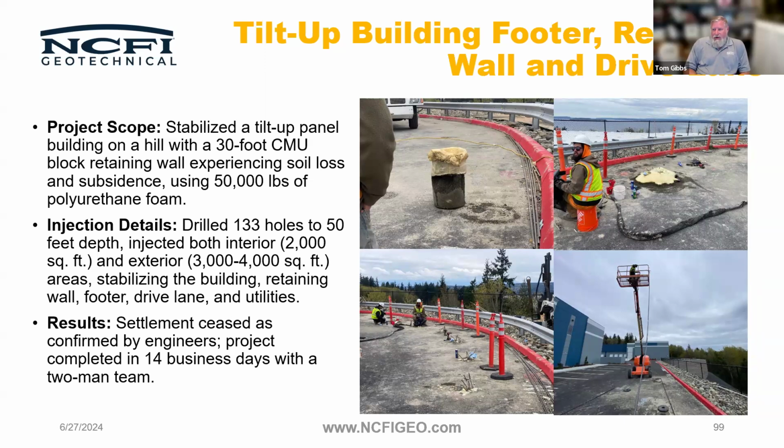But if you were doing one where there's literally no concrete or even asphalt, which is a rarer job, but it happens, like in a curtain wall situation, the freeze thaw can actually start to push those pipes back up out of the ground. So try to get them down deep enough. A lot of times they'll be locked in, but sometimes they can creep back up on you.